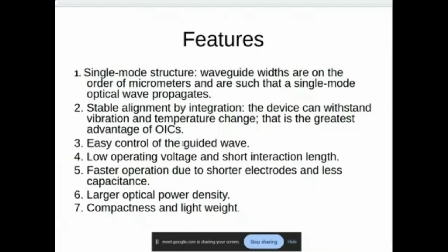Many of you know about the power densities in an optical fiber. If it is 9 microns and you are transmitting a fraction of a milliwatt of power, the intensity is very, very high. Some calculation will show that it is about 500 times sunlight. Daylight, if you take it, you feel is very intense. So the light going in an optical fiber is very intense compared to daylight also. A caution from the laser safety people is that you should never operate without goggles. Even reflected light falling onto your eyes or skin is not good.